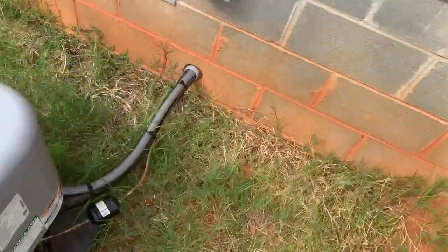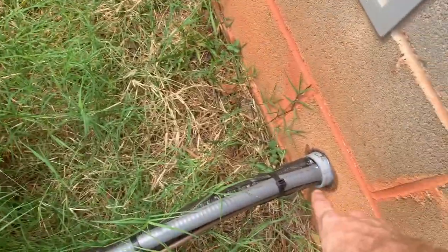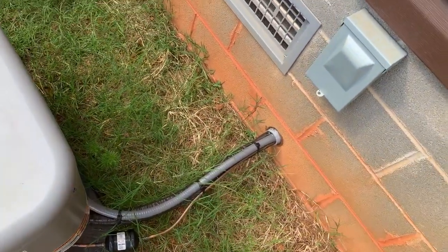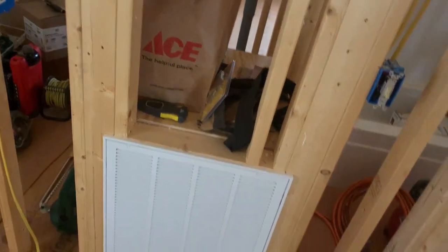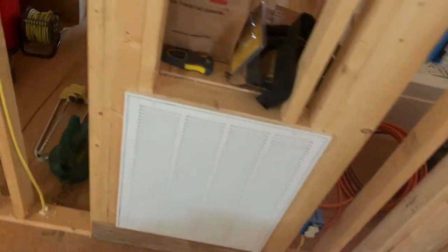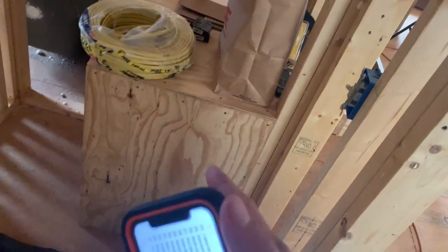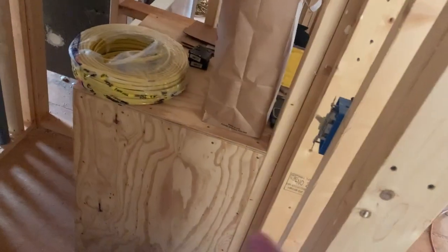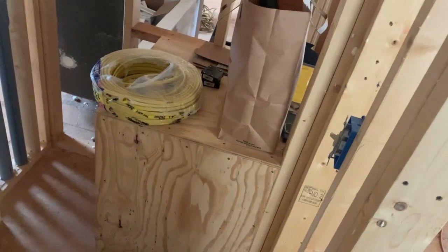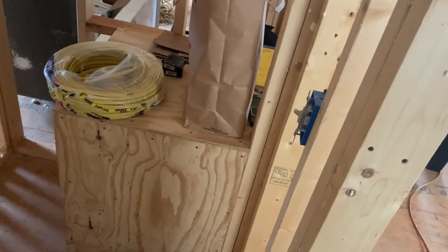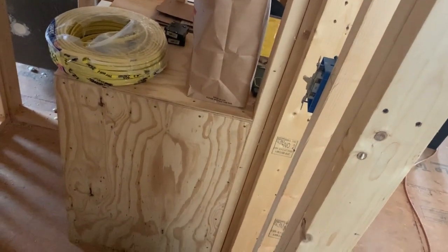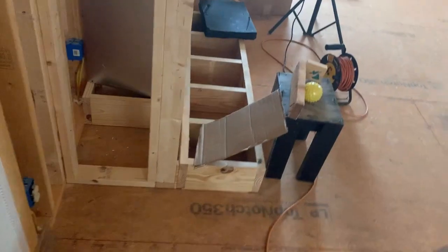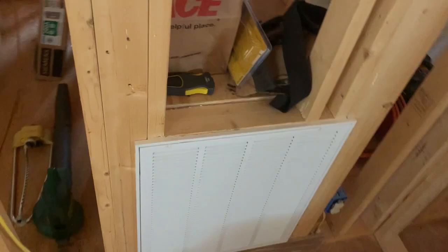So the flexible conduit I was talking about just goes from here, just inside that, so that it doesn't get water in there. Then we built the air return here. Obviously we had the hole framed out already for the vent. And then we had to frame out the box, cut the floor out, and put blocking in between the joists to seal off the box in between the joists there.